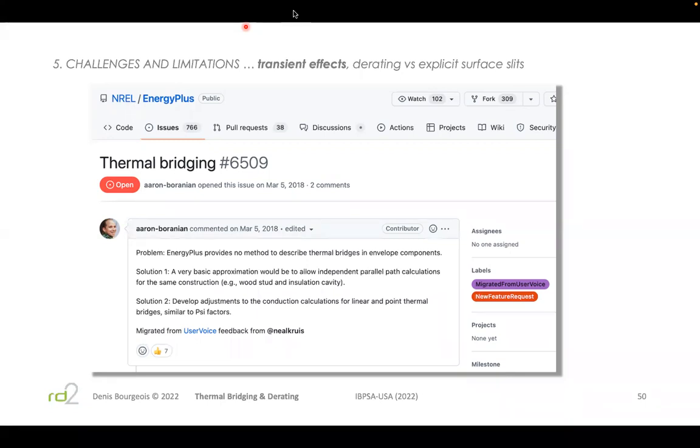But in reality, especially on the building stock side, we're coming to the conclusion on a regular basis that there's no physical solution or no cost-effective solution. So no, my initial assessment is that the 2017 and 2020 codes haven't lowered the R value in order to factor in the additional thermal bridging.